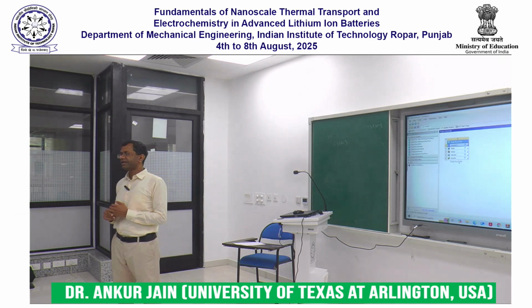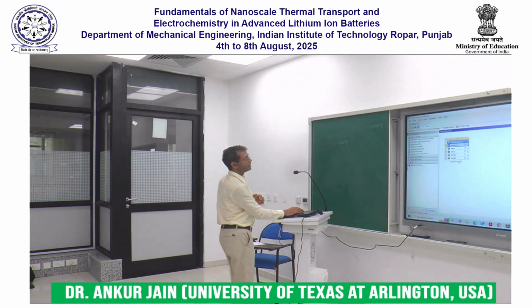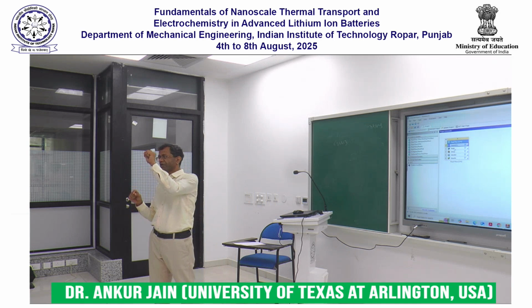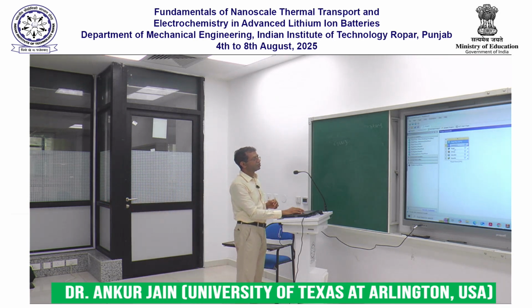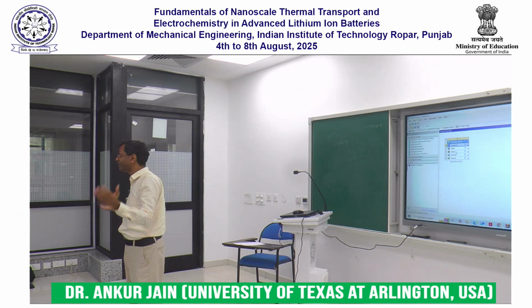All right, and the way this flow will work is very streamlined. It says, tell me the geometry. Oops, where is my mouse? There. Tell me the geometry. After that, help me mesh the geometry. When it says mesh, it basically refers to that process of breaking up the body into a number of nodes, right? So Ansys will ask you, how many nodes do you want me to put? Where do you want me to put those nodes, etc. After you've taken all those decisions, then you will go to setup, where you will basically tell Ansys all the information it needs to define the problem.